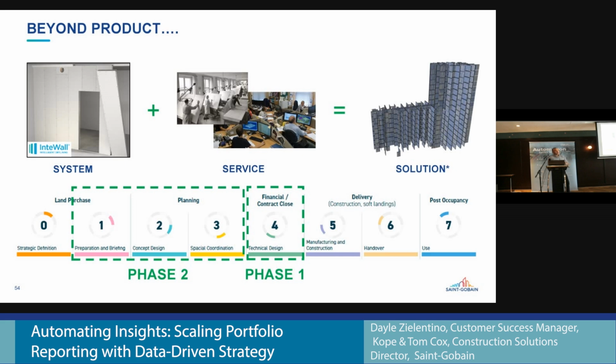But when you're looking at it in the round, there are huge cost savings in terms of site sequencing, cantilever lift operations, crane lifting, waste operation on site, and the control of product coming in and being managed at site stores. With these sorts of products, they turn up on a lorry, there are 4 stillages for an apartment, which is lifted in 1 lift, and then 4 empty stillages fold flat and come out on site. There are no multiple deliveries from multiple suppliers that are managed and then have to get to the coalface, paying someone to create waste to take away.